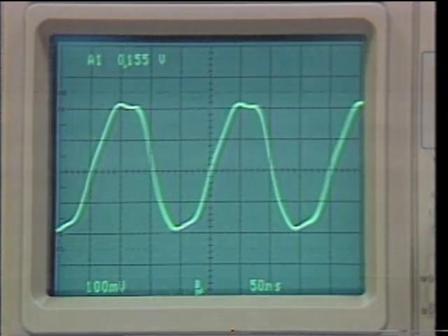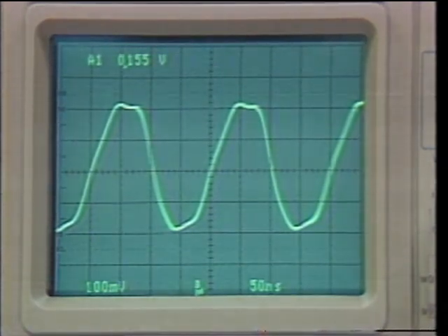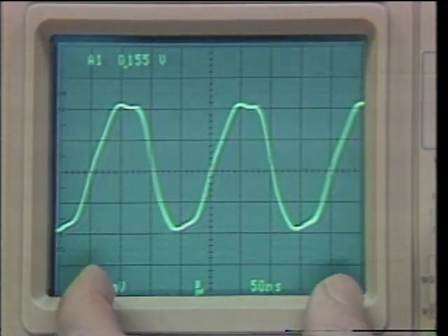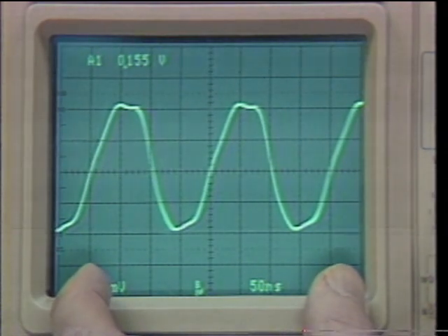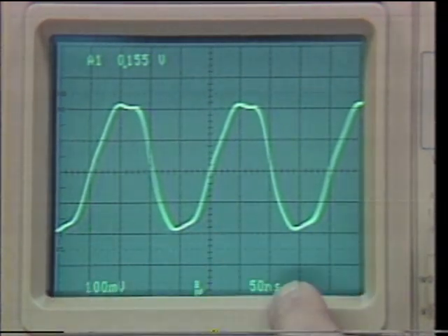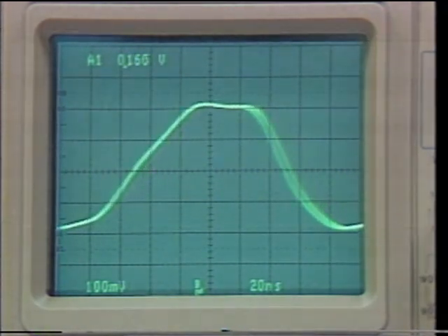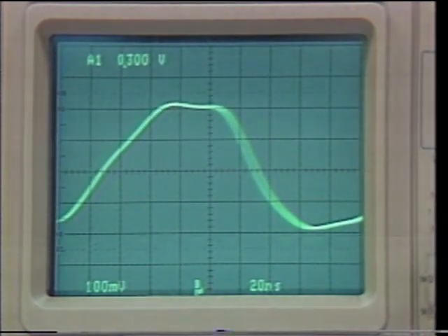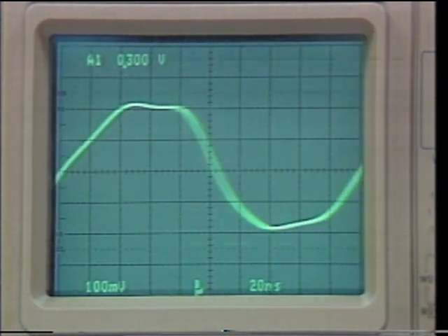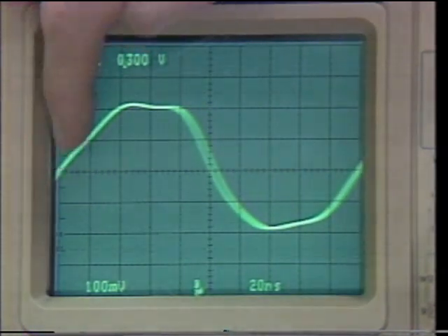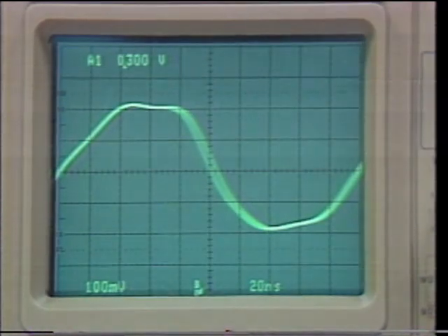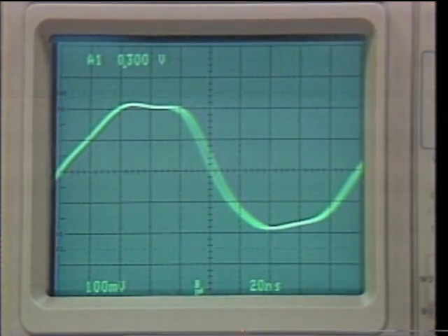Here we know the period is 200 nanoseconds, and so we look at the center 8 divisions, which is 400 nanoseconds at 50 nanoseconds per division. At the next speed, we'll need to change our trigger level and horizontal position so that we can align the rising edge with each of the outside edges of the graticule, to verify 20 nanoseconds per division.